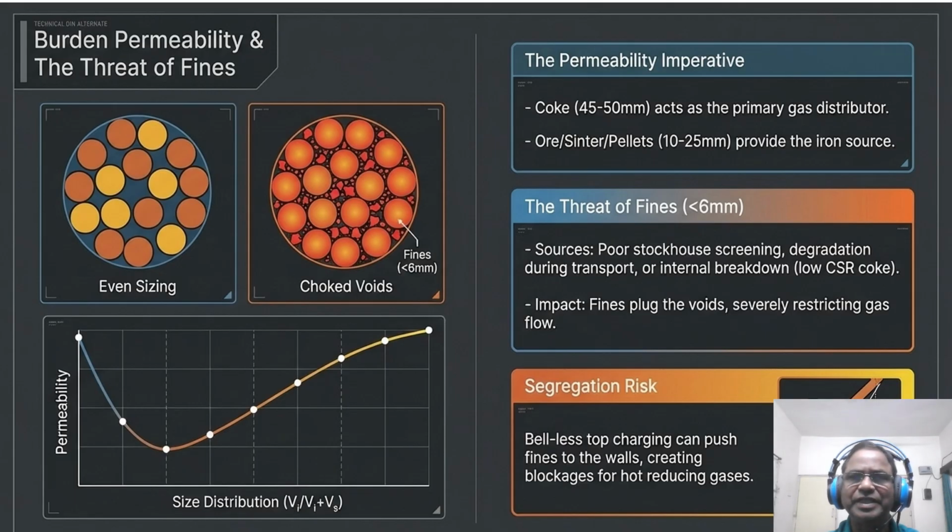As we have seen in an earlier presentation where the Ergun equation is shown, a tiny amount of fines could contribute to an immensely high delta P, and if we cannot stabilize those delta P timely, then fines generation in the furnace will automatically keep on increasing, which will have a detrimental effect